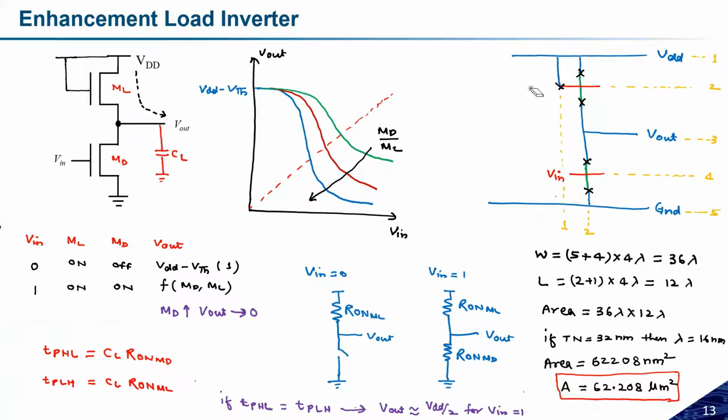Sir, I'm just asking, the blue line you have connected to the polysilicon in the upper network can be replaced with polysilicon, not metal. Yes, it can be replaced with the polysilicon, but the area will be the same, because it requires something. Either you can make it polysilicon itself, or you can have this polysilicon and this metal. Both are possible. So you don't need one more contact point, but you need a contact point over here, right? So there is no problem. The number of contact points will be the same.